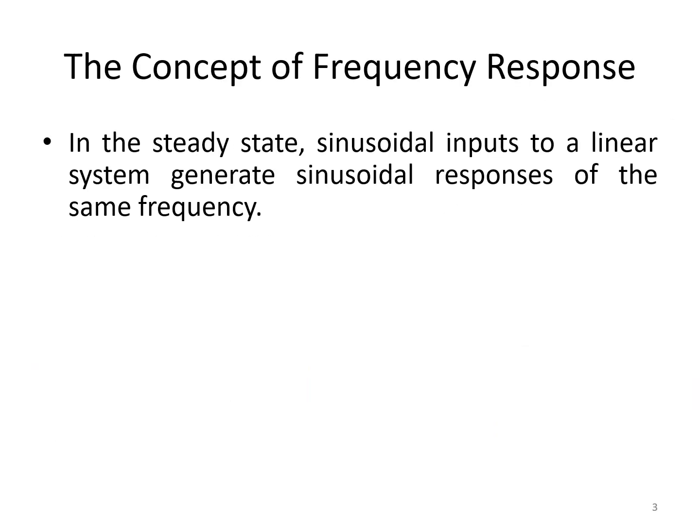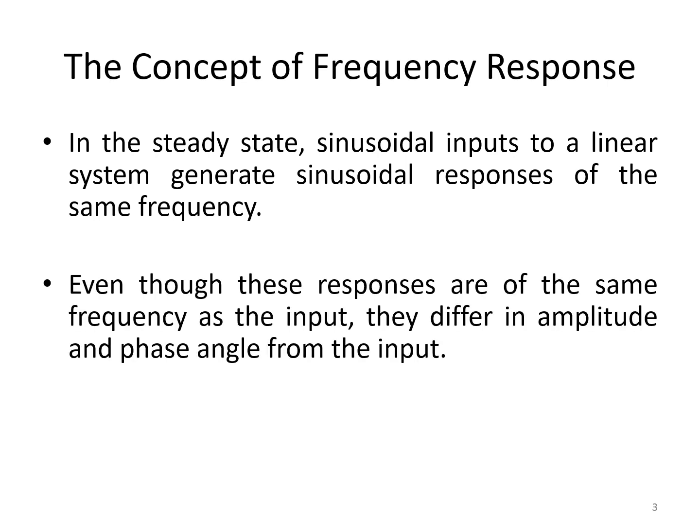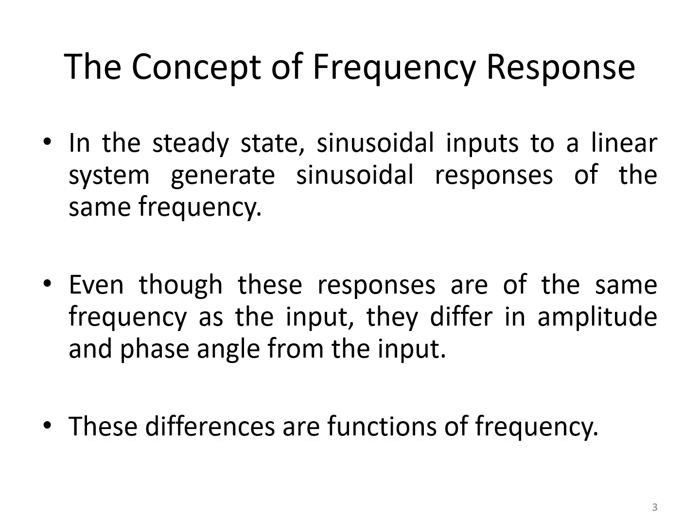Now coming to the basic concepts of frequency response, in the steady state, the sinusoidal inputs to a linear system generate sinusoidal responses of the same frequency. Even though these responses are of the same frequency as the input, they differ in amplitude and phase angle from the input. So these two are the things which are going to change in the output response, that is amplitude and phase angle. These differences are determined with respect to the frequency value and are treated as a function of frequency.